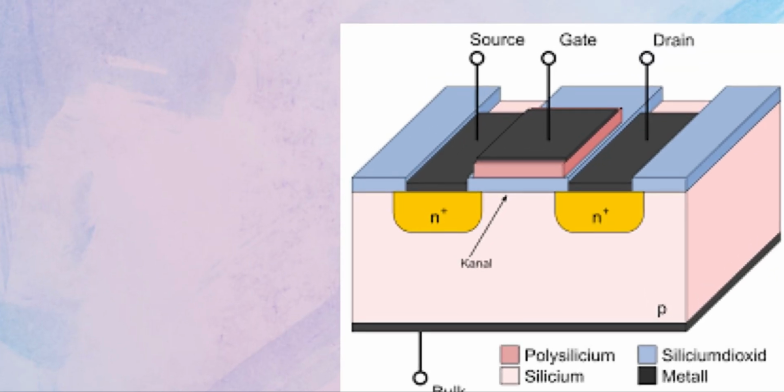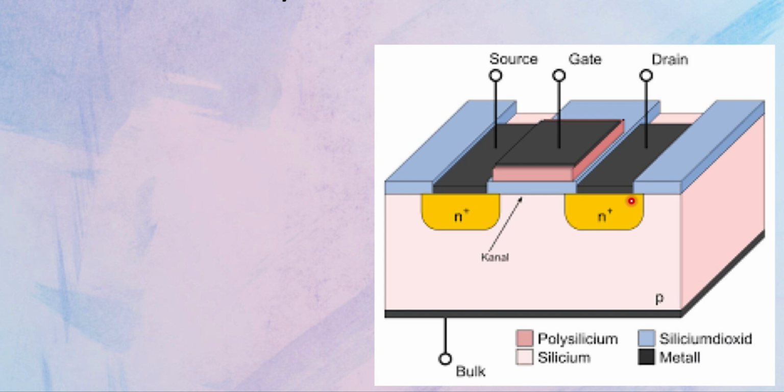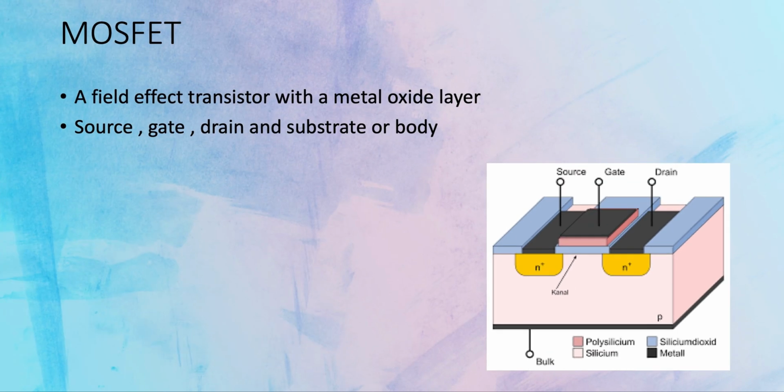Now why do we use a silicon dioxide layer over here in a MOSFET? This is because silicon dioxide usually insulates or isolates the metal from the semiconductor. Do you remember that we saw the Schottky diode? It's something more like that, except that a Schottky diode is 2-terminal and a MOSFET is a 3-terminal device. So we don't want the charge carriers in the gate and the semiconductor to recombine with each other.